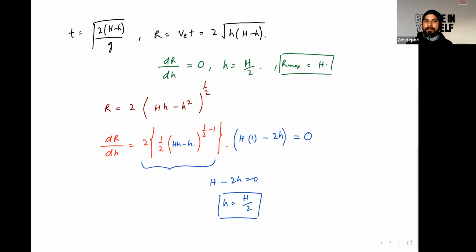Is it clear now? Yes. Okay. Now suppose you are given that the level of liquid in the tank is up to 4 meters, or 2 meters. At what point should a hole be cut out to have maximum range? You'll say it will be at the midpoint. So according to the measurement, just divide by 2, and you'll get the position of the hole.